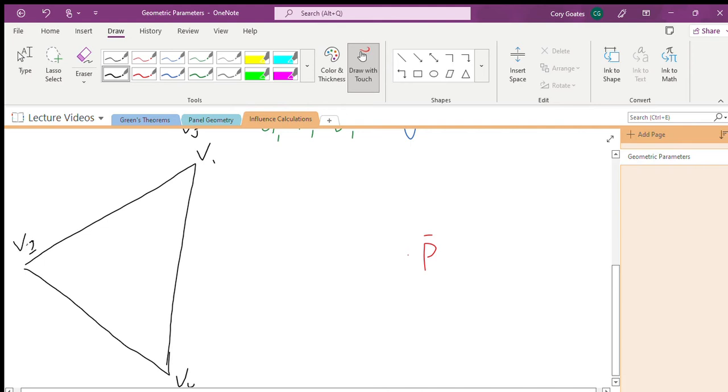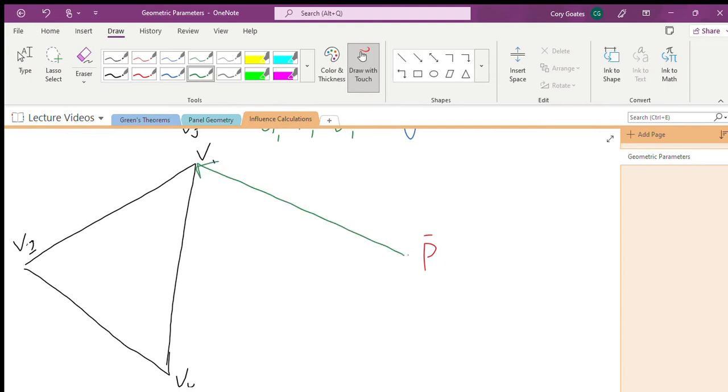We could draw, here are our radial displacements projected down into that plane, R0, R1, and we've got A here. The final set of parameters that define this edge are tangential displacements. So we've got perpendicular displacements, now we need to know tangential displacements.